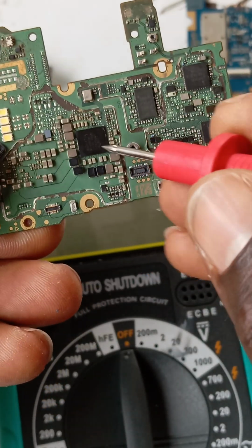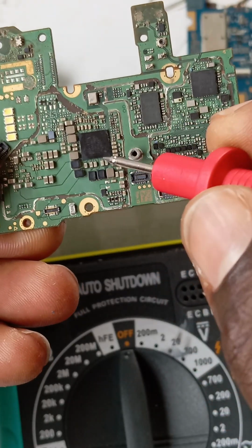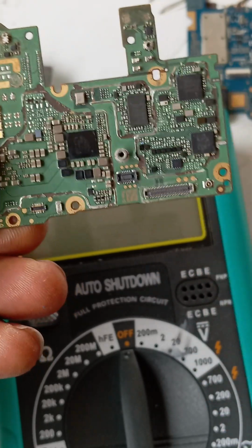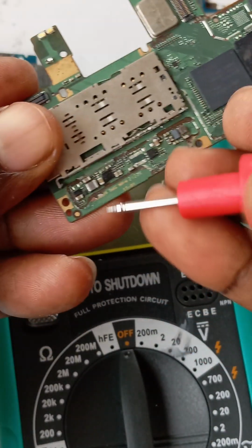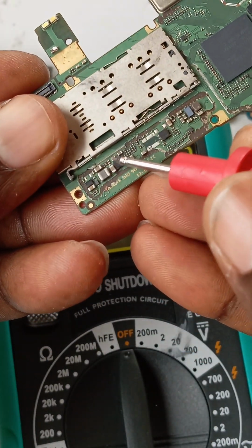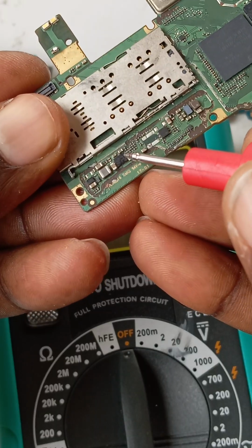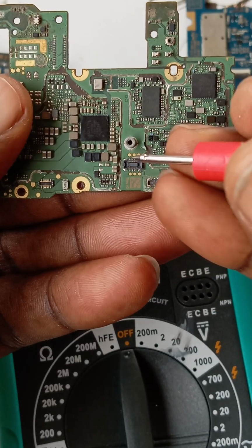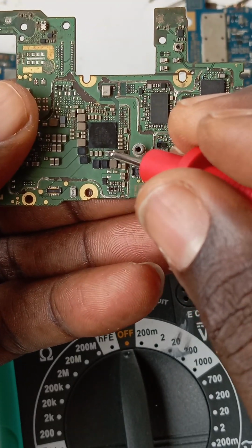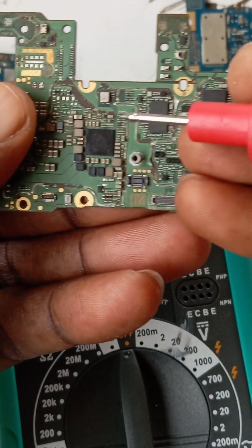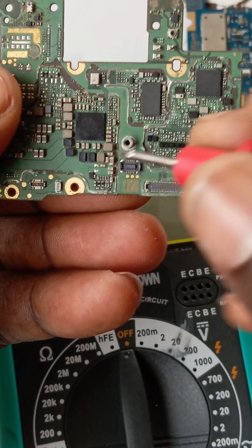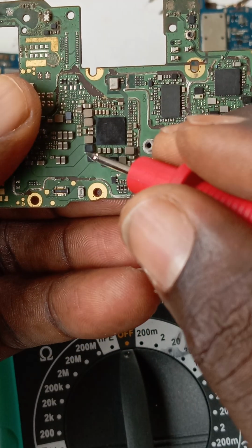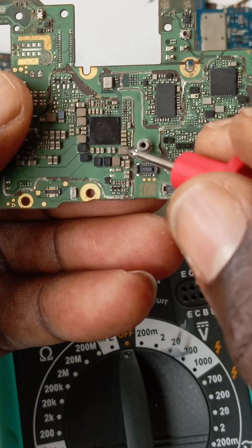Now, these capacitors here get the input voltage that is required to power the power IC from the charging IC. This is the charging IC. How can we know which component is bringing the voltage to these capacitors in order to supply the power IC? In most cases, you always see these capacitors close to these coils. They are always at the side of this coil.